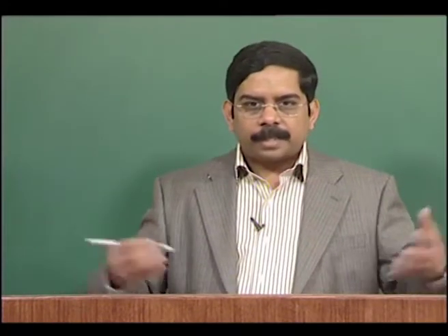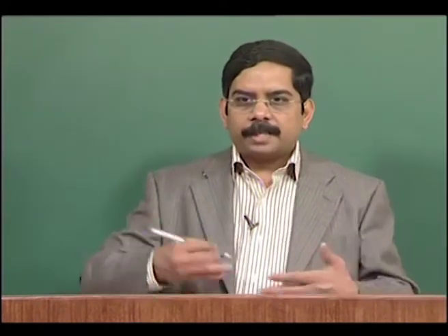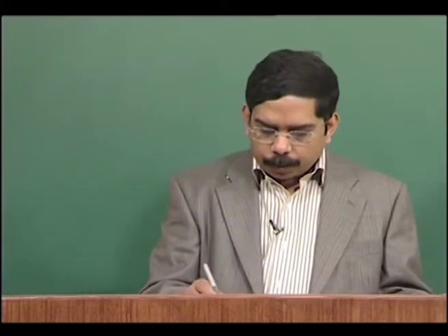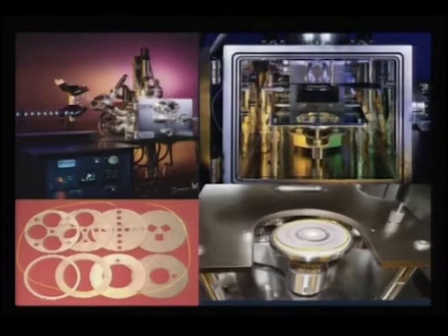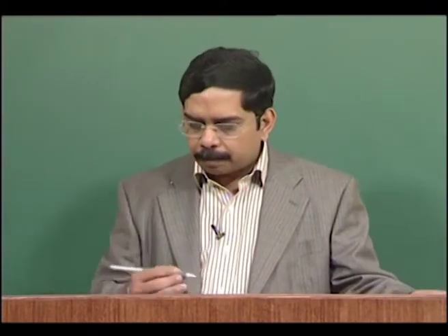But not only that, you can also use a multi-target holder. So if you want to make a complex material like what I showed in the previous slide, bismuth strontium copper oxide, you can even start with individual oxides and try to judiciously make such a layered compound, and that's why you have different target holders with different fashions. So you can actually mount more than 6 or 7 at a time, and with computer monitoring you can switch between these targets and try to make complex oxides. All these are possible in a PLD chamber.